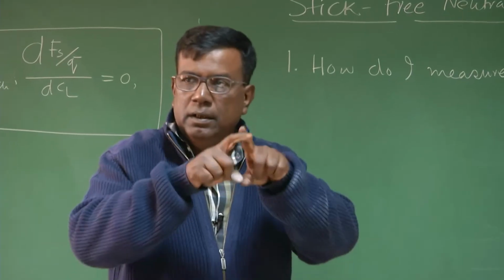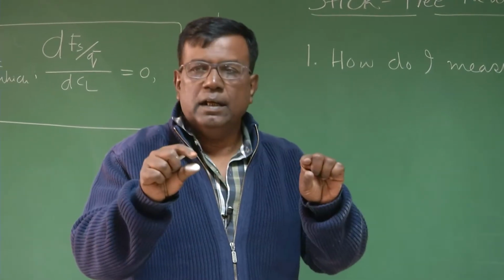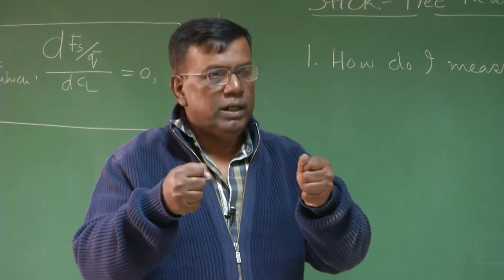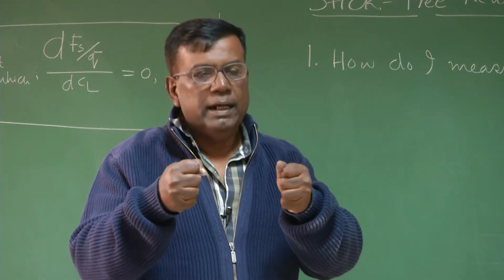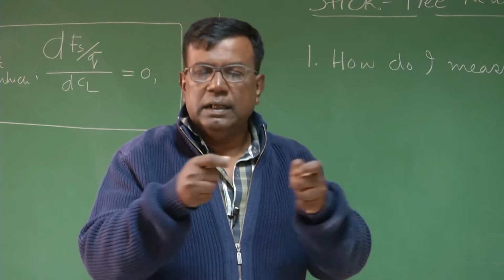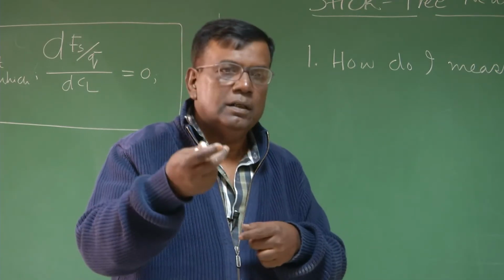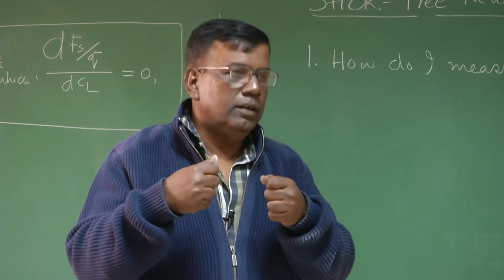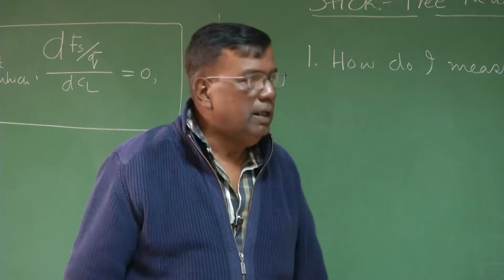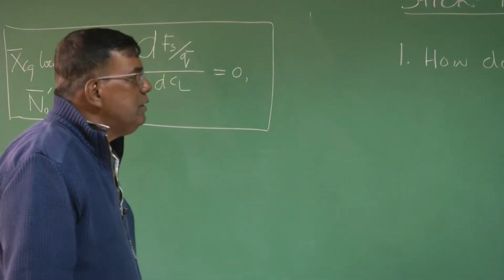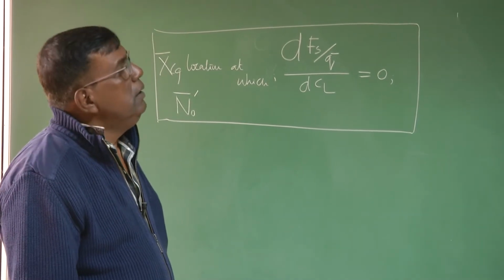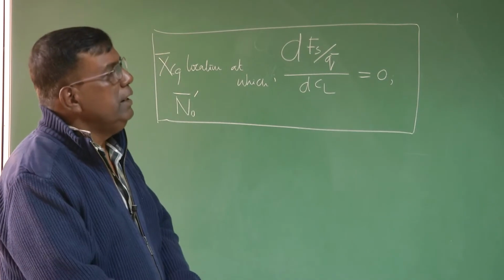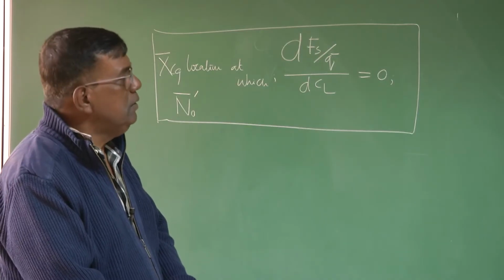You have the stick, let's say a stick like this. The strain gauges are on the stick. So as I pull it, there will be bending, there will be stress developed, and through the strain gauge measurement, I can find out how much force has been applied in terms of a pull or a push, right? So you use the strain gauge principle. You also use a Wheatstone bridge. That is how, through strain gauges, we measure the stick force.